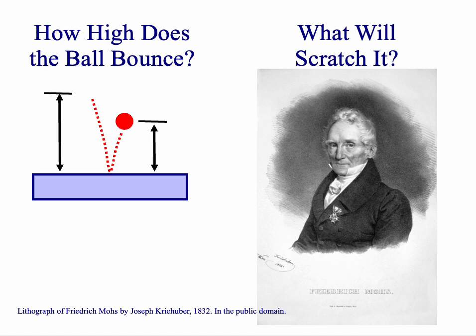There are portable hardness indenters that measure how high a steel ball bounces off the test material. These hardness testers are not as accurate, but because they're portable, some consultants like to use them. What you really have to watch out for is results converted to a standard scale. Hardness tests should always state whether they're actual readings or converted readings.